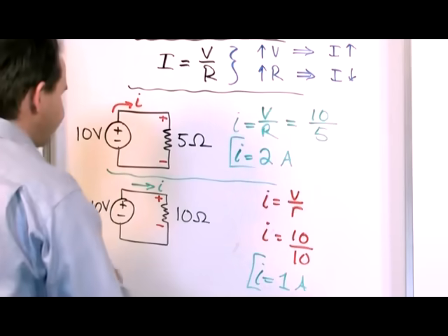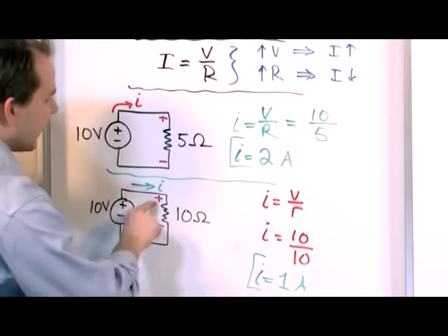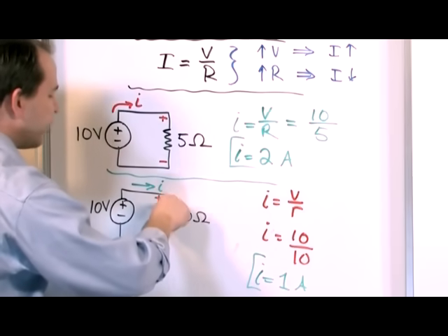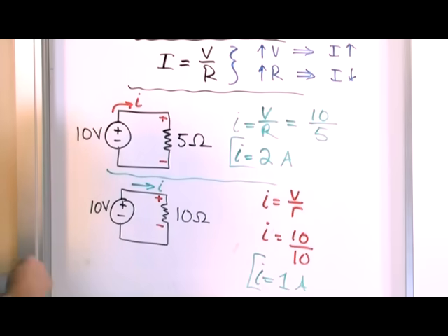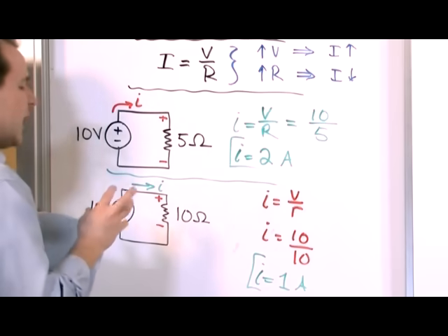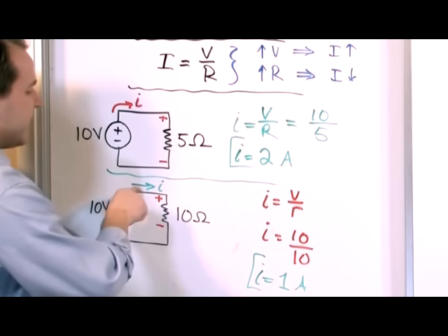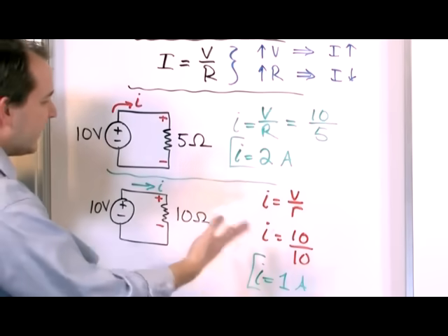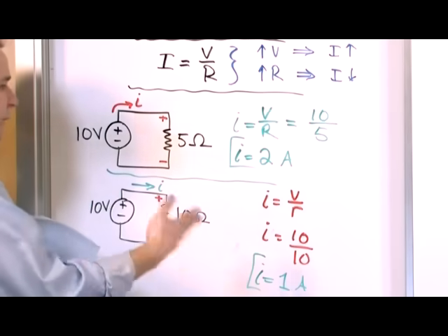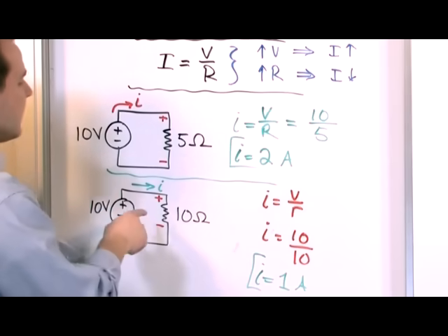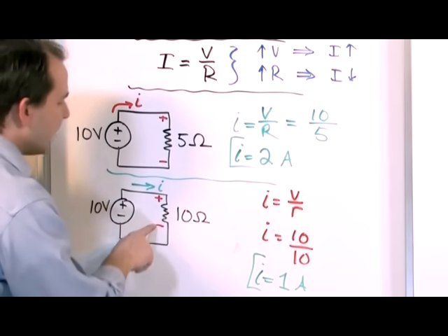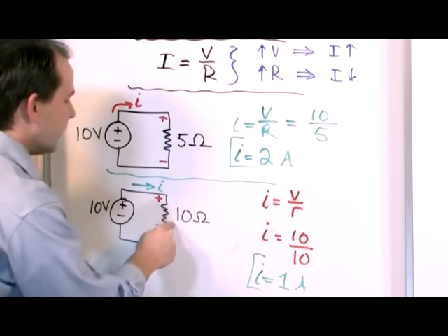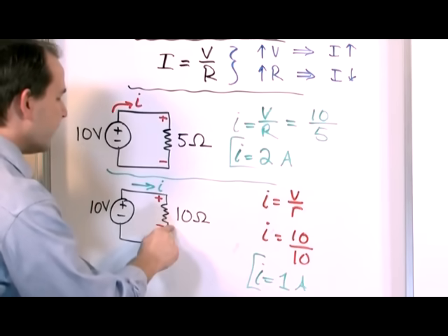You need to think of it as almost like the voltage across the resistor is what pushes the current through this resistance, for lack of a better word. And the way we do the sign convention in engineering is that whenever you're talking about a passive component like a resistor, a capacitor or inductor, everything we're going to talk about is called a passive component, then the voltage drop, we call it a voltage drop for a reason, goes in the direction, positive to negative, of the current flow.